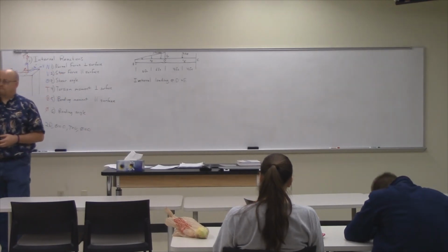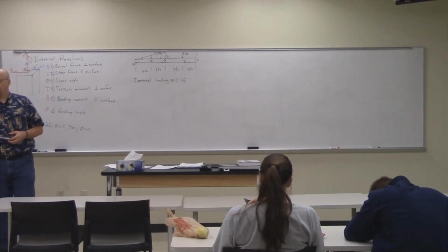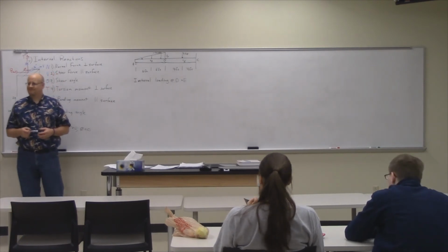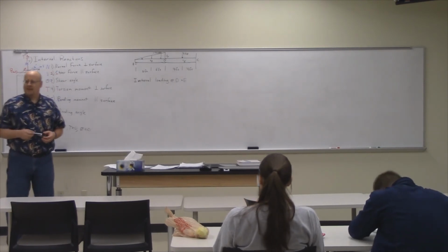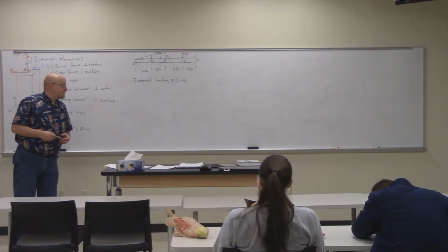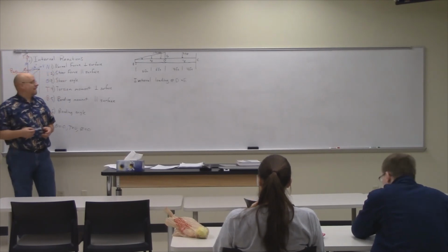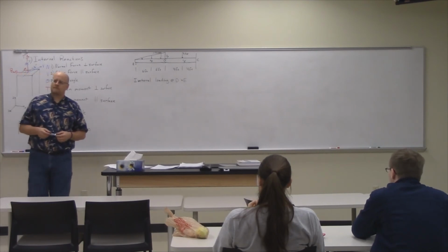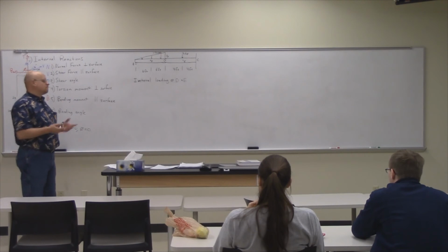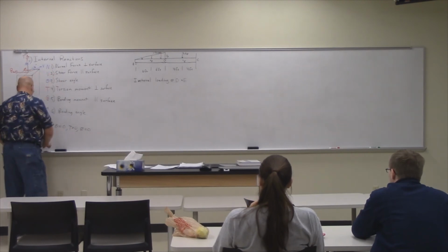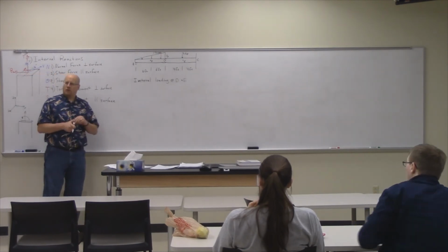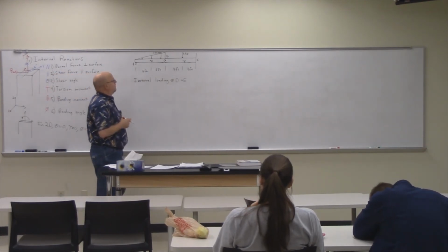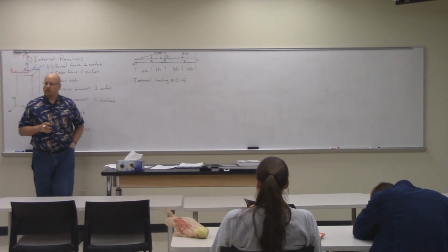What's the first step? I take the integral of the distributed force and find the centroid of that shape of the distributed force and turn it into a point load. That was my first choice, but that's an allowable first choice. So you have 1.5 kip per foot. What is the resultant force going to be?